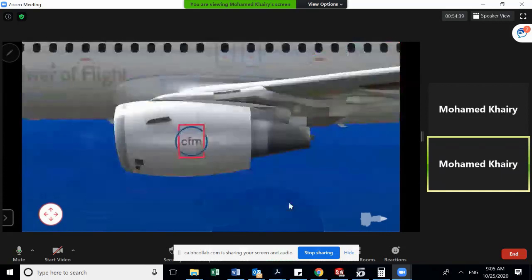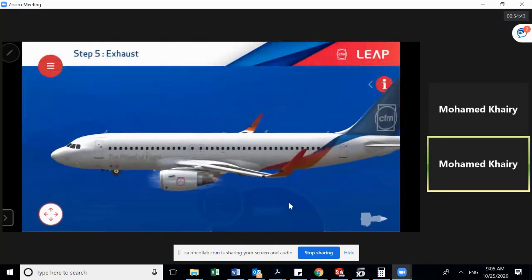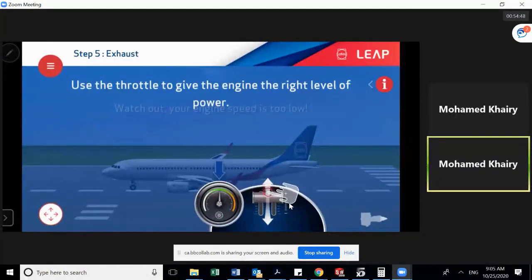Okay, right, now let's see. This is the airplane, and this is the engine connected to it. You are going to see this in the flight phases in performance. So the first phase of the airplane is taxiing on the runway. After that, the pilot will give full throttle, full power to move the airplane, to let the airplane leave the ground. Then when it reaches the altitude which we call the cruise altitude, the engine thrust should be decreased to a certain level, according to many factors like the airplane weight, the number of passengers, the density, the altitude. You are going to put the throttle at a certain setting. It should not be at the maximum, otherwise you will consume a lot of fuel and even the turbine will not withstand that high power.